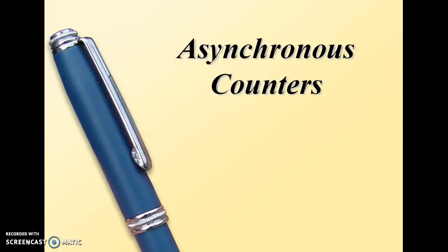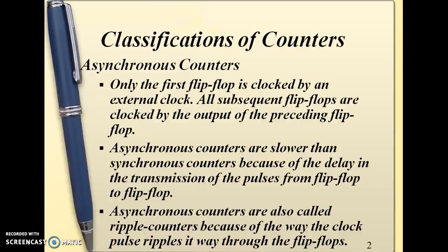Good morning. Today let us discuss asynchronous counters and their design. First of all, let us discuss the classification of counters. Counters can be divided into two: asynchronous counters and synchronous counters. In an asynchronous counter, only the first flip-flop is clocked by an external clock. All subsequent flip-flops are clocked by the output of the preceding flip-flop.